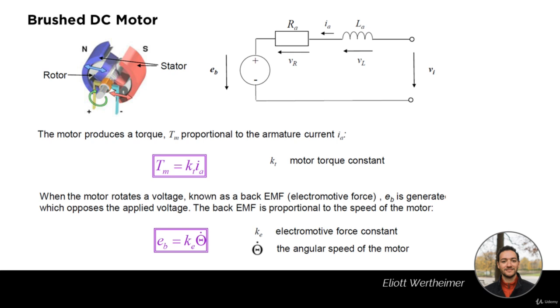Just to make it clearer, guys, the back EMF is actually a voltage created by the motor itself when it gets rotating faster and faster. That voltage is opposite to the voltage that is applied to the motor from the battery or the power source, and therefore effectively is decreasing that external voltage. So the faster the motor turns, the less effective voltage it is seeing. So it's actually what limits the velocity and the power of motors. It's that back EMF which grows as the motor turns faster and faster.